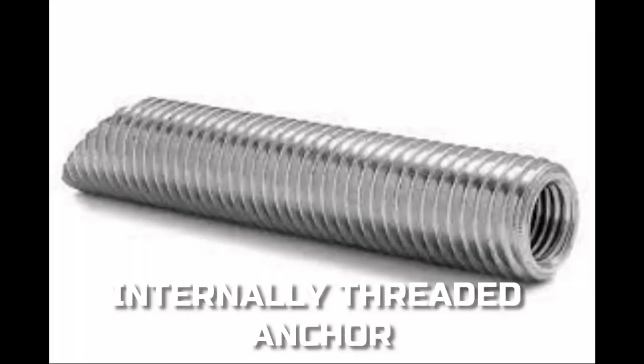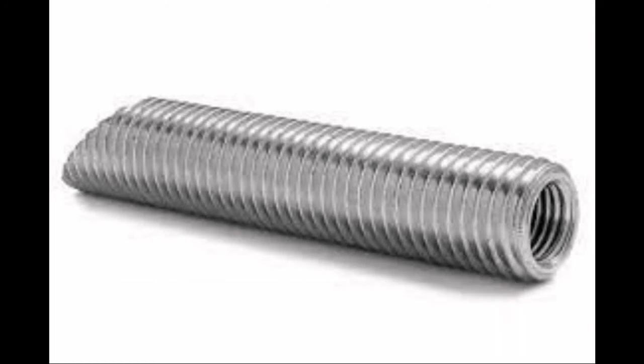Internally threaded anchors. Internally threaded anchors are used with machine screws, cap screws, or threaded rod, and are designed for concrete, block, brick, and stone. A setting tool may be required and they are not removable or reusable.